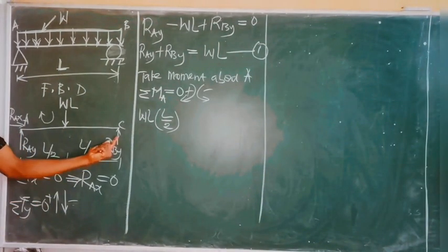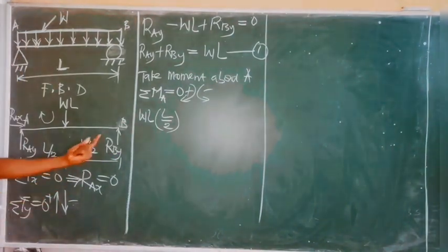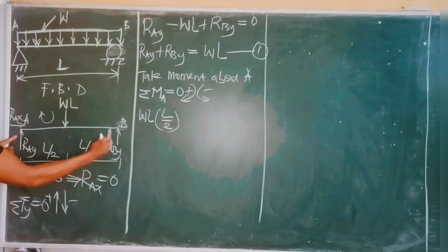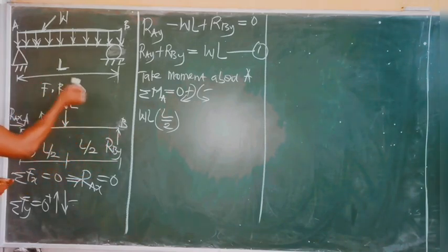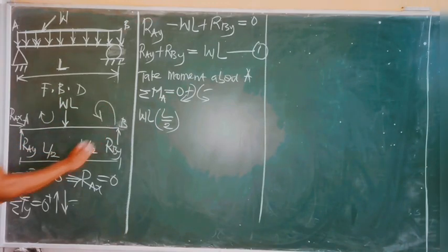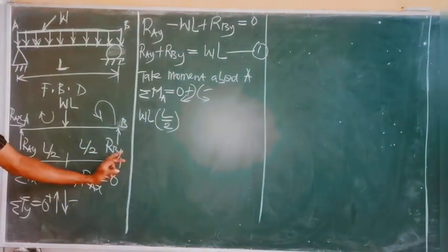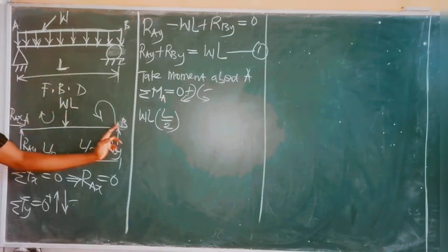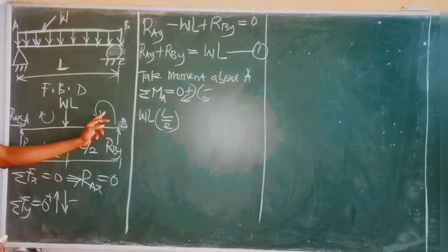Next moment to take is moment of point B, sorry. This is point B. Sorry about that, okay? So next moment is moment of point B about point A. All right, so if I take moment of this force about point A, this force is pointing upwards. So which means it goes all the way in this direction. This is the line of action of the force going upwards. So the moment goes all the way in this direction. And if you notice, this is anti-clockwise to our direction. So which means the moment of this force about point A is negative. And the distance it takes this force to get to point A is simply the entire length of the beam, which is L. That is moving from point B down to point A. You have L over 2 plus L over 2, which simply is L. Okay, and it's negative because it's anti-clockwise.